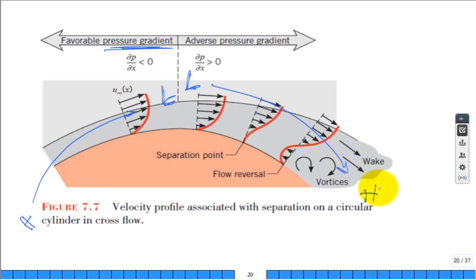But guess what happens in fluids? And this is why fluids is a hard class. A lot of people struggle with fluids. Can you have flow go from low pressure to high pressure? A nozzle makes it accelerate. A diffuser makes it slow down, and when it slows down, it builds pressure. From thermo as well as other classes, fluid mechanics, you can go from low to high pressure. But fluid particles don't like to do that. So this is what they call a favorable pressure gradient. They like to accelerate. Everybody's happy.